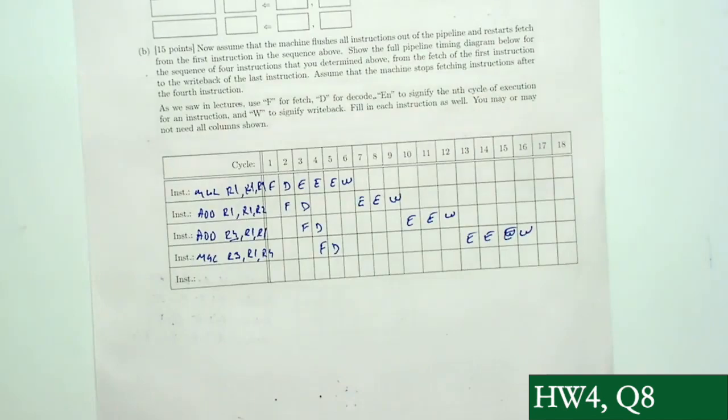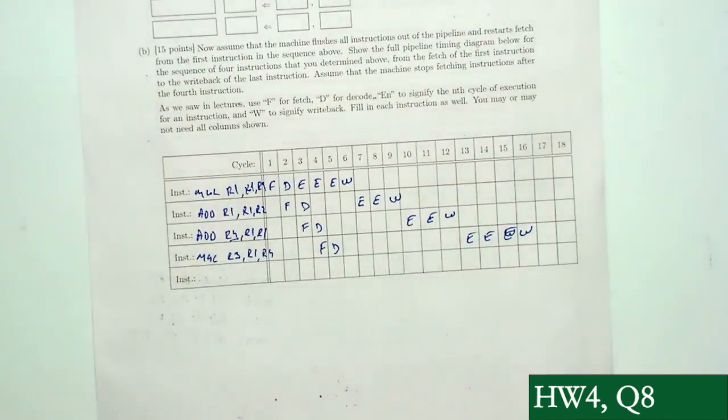Let's take a look at the last part, unless you have any questions. I don't see how the third instruction could get into decode. No, wait. It leaves the decode stage and goes to the reservation station. So decode stage is free again, right? Yes. Okay, then I understand. Yeah. So this is slightly different from in-order execution, where usually we do the register fetch, fetching the source operands at the decode stage. So here, that's not happening at decode, right? You are not accessing necessarily the register file at decode. You are just allocating a reservation station entry and filling it accordingly with all the dependencies.